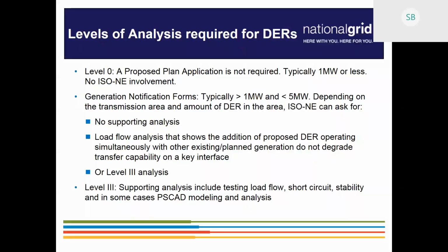the fault duty capability. It's understandable that inverter-based generation does not have the same contribution of fault duty as conventional generation, but when you look at an aggregate in a respective area, that's something that we need to evaluate to make sure that in aggregate the fault duty is not significantly impacted, that will require additional upgrades to our existing breakers. It also requires the stability analysis.